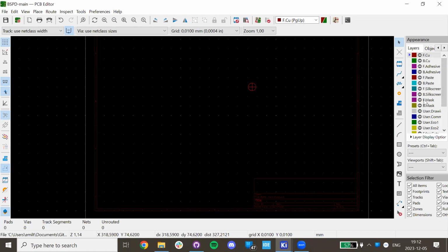And if you have mask in between, which is like some non-conductive, well, you could call it like some plastic in between, then it makes soldering easier, for example, because if you have some metal only in between, even though it's not the same net, or it's maybe just some floating metal, it's just copper in between, there's still a much higher risk that you short 2 pins. So by getting mask in between, you prevent that.